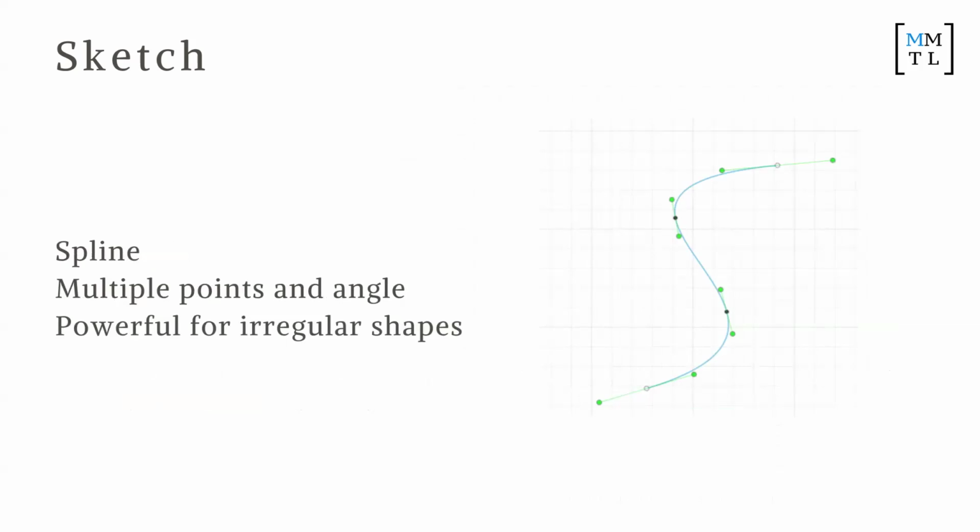So the next tool we're going to use is spline points. So spline points is more of like a free-form way of sketching. You're going to make different points, and the computer basically automatically generates curves between these points. So you can try using spline points for that. We're going to delete all these sketches later on. So try using the spline point tool.